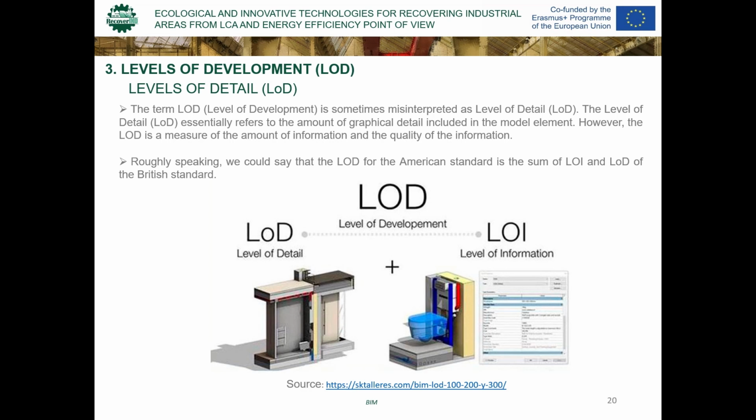The English standards and publications PAS 1192-2/3/4 and BS 8541-2011 define these levels. A, B, C: schematic, conceptual and defined. G0 symbolic. No scale, simply a suggestion of where the object will exist. For example, in the case of doors, this could simply be a black rectangle on a 2D wall.